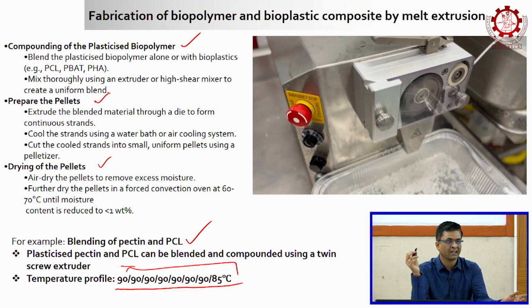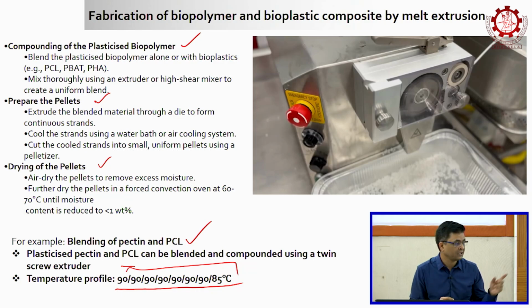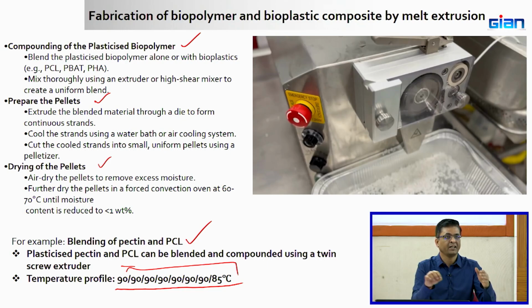Recycling does not mean that you use the same bottle again and again, that is reuse. Recycling, if you remember when we were talking about recycling, upcycling and downcycling, we said to create a material of similar or lower properties. So, this bottle is melted, something like wax in a wax candle, where you take leftover wax, melt everything and then make your own candle. Very similar way, this plastic is melted with a different, higher temperature profile, made into a string, and just chopped, and that plastic can be used to make a film or a sheet.